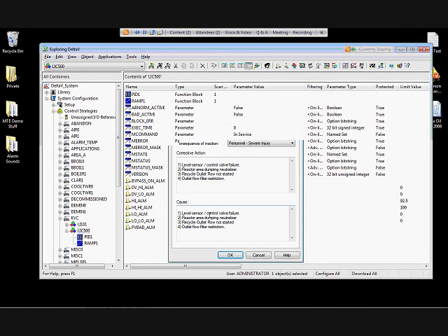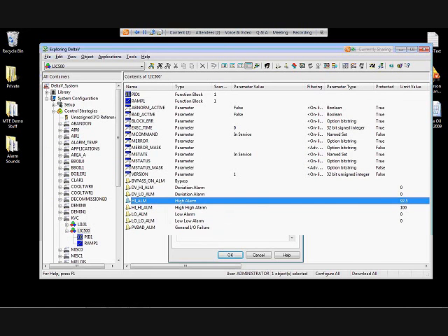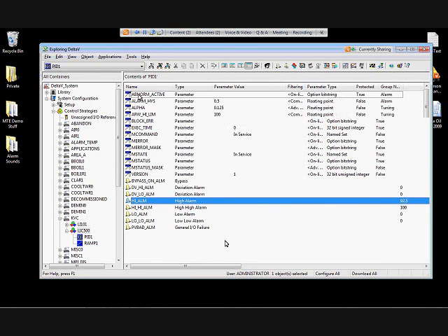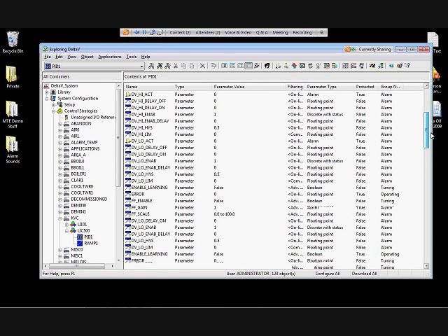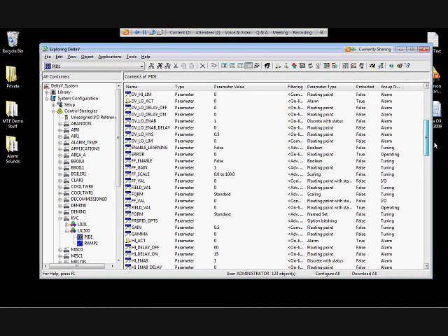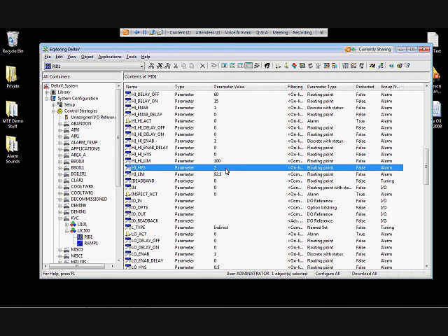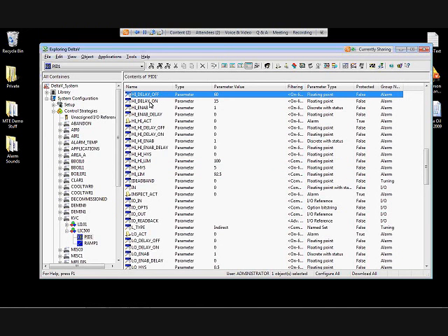In terms of the alarm conditioning, there were some decisions made in rationalization to use some settings there. So let's just see if they came through. Here we have the high alarm hysteresis, which was formerly 0.5%, a little low for a level loop, and here we put 5% in. And I see that there is a high alarm off delay of 60 seconds, and a high alarm has an on delay of 15 seconds. So it appears that everything is completely successfully transferred into DeltaV.